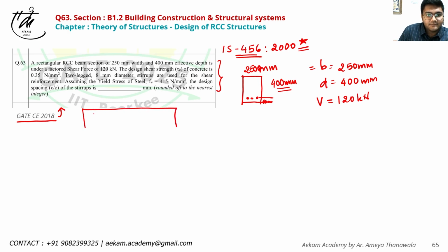If this is a beam, a beam will definitely have its longitudinal and transverse reinforcement, the cage of reinforcement which is there. But in addition to this, there are these lateral shear stirrups, which prevent the beam from shear failure, and they are generally located close to each other near the supports or near areas where the shear stresses are maximum.